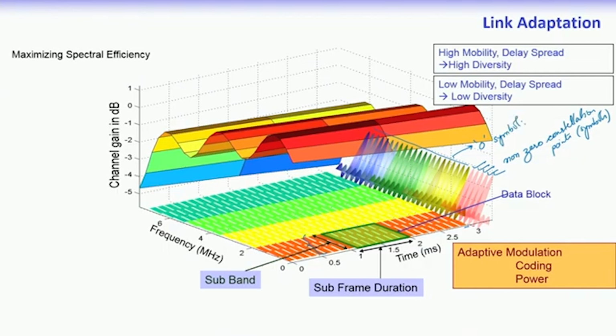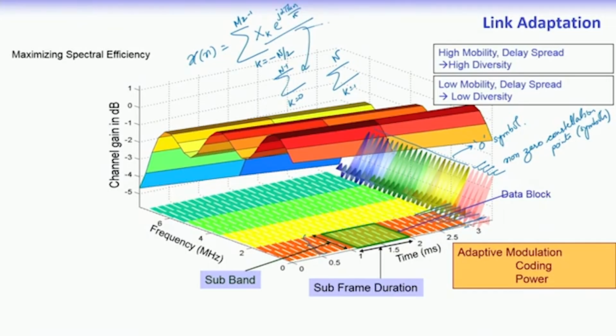Okay. So, effectively the active number of subcarriers is restricted to the band of subcarriers allocated to that user. So, when we look at the IFFT operation at the transmitter, the x n, which is summing over k equal to minus N by 2 to plus N by 2 minus 1, or let us say summing over k equal to 0 to N minus 1, or you can also sum over k equal to 1 to N, in all these cases, x k e to the power of j 2 pi k n upon N, that is valid for all the cases.